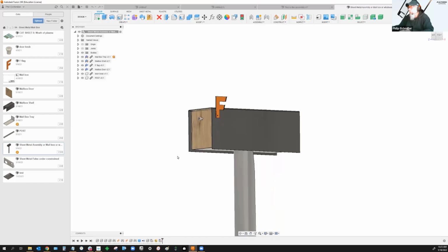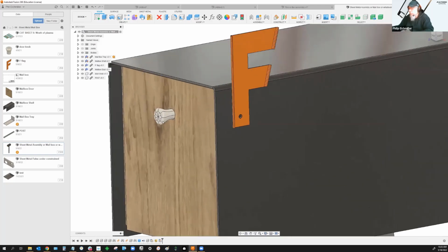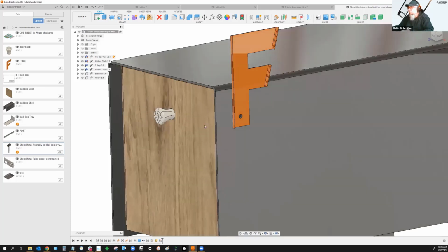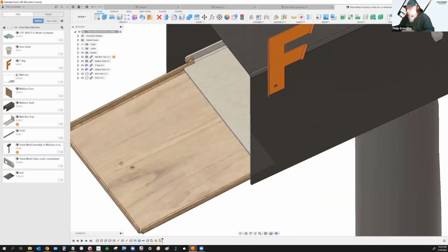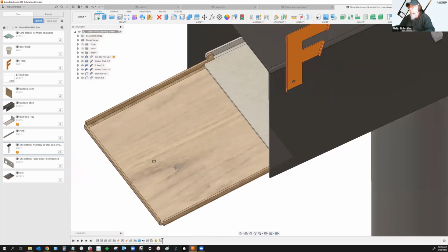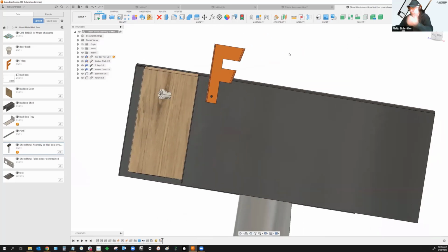Yeah, so most of the stuff, this moves and this moves, right? So obviously I need joints there, but what if this mailbox got taller? Or let's say it got taller, the door would get taller, and then the rigid joint between this knob and the door would be what keeps the knob in position around the hole that it's positioned with, right? So absolutely joints are required in this case, in case I make either motion by opening the door or possibly a parametric edit where that hole that mounts the knob would move. So to make that connection together, you have to have a joint.